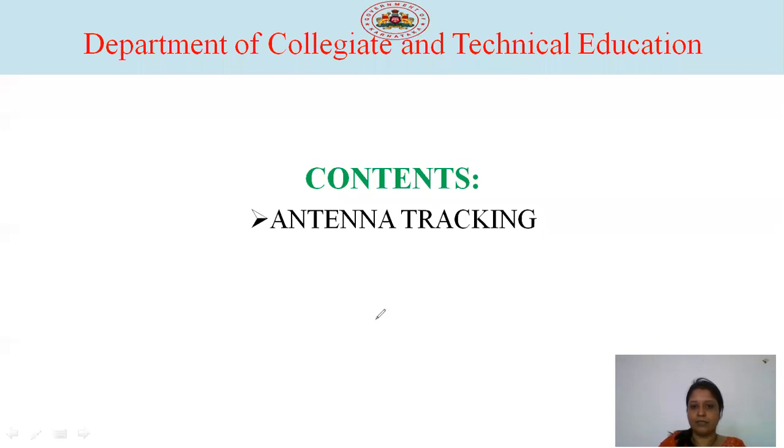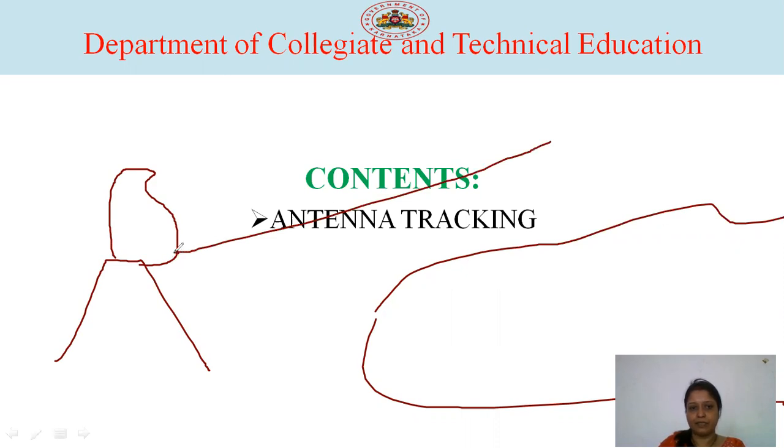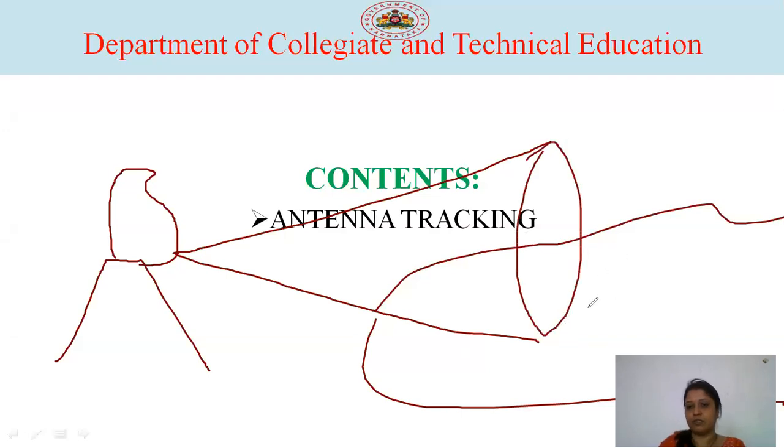now see here, suppose this is the given region, in this region, to search the target, from the particular antenna we are radiating, we are scanning the region here. Scanning means searching for the target. Therefore, a very wide fan shaped beam signal is radiated such that it will cover a large amount of area at a single time, and it is searched whether any target is there or not.